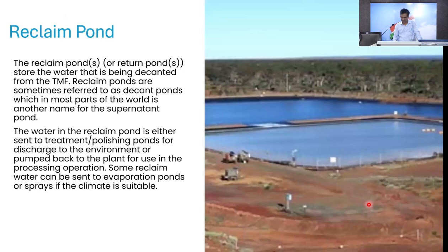Okay. So this is a reclaim pond. Reclaim ponds are there also in some of our industries, like red mud and others. They have got the reclaimed pond. That means I can pump this water to a pond dedicated for this extra water, from which we pump it. It is used in steel and aluminum industries, but we don't use it for the thermal power plant, where we have got plenty of water. Sometimes we keep one chamber with water and make the other chamber dry, and alternately use them.